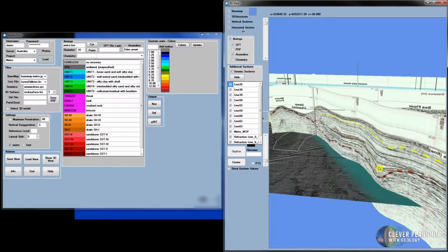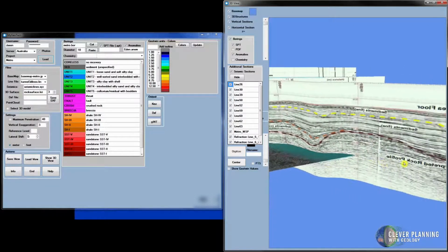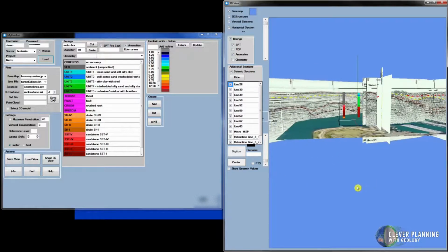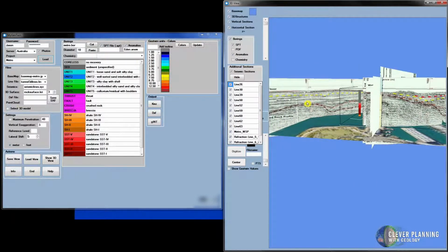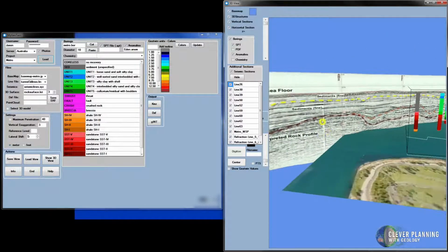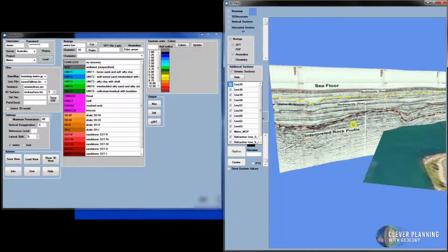These analog seismic sections are all individually hand-processed. This is a major difference with advanced digital imaging. Advanced digital geophysics is machine-processed in just a few hours. And here we have analog data where the geologist has had to hand-draw what they think are the relevant geological units and then relate them spatially to neighbouring sections that might be tens or hundreds of metres away. Here we have 3 sediment structures and rock interpreted across the site and then surfaced independently.